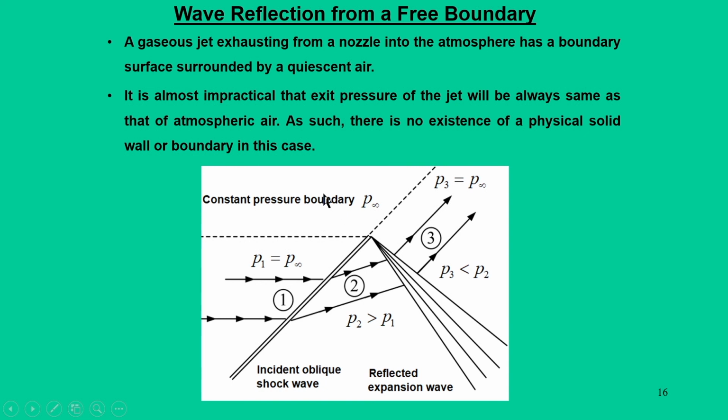That means the streamline is going to get deflected through this corner. So, these streamlines get deflected, and accordingly we will have a situation in region 3, and region 3 also must match this pressure condition, that is P infinity, and the flow deflection line should also follow similar directions, so P3 must be equal to P infinity.